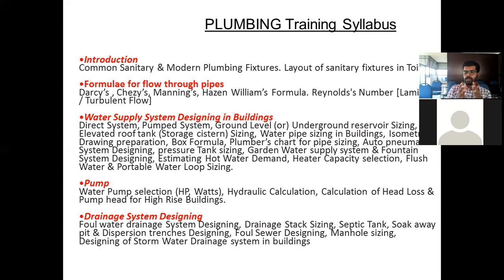So you need a pump. Once you have the water from the well and from the underground tank, you just pump it to the overhead tank. The water will be stored in the overhead tank, right? That valve is known as a foot valve. If you are using a centrifugal pump, there will be a foot valve.